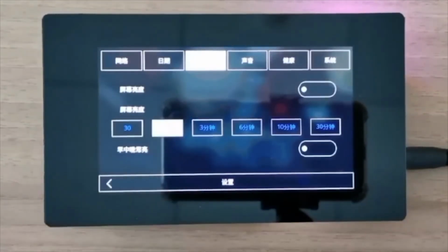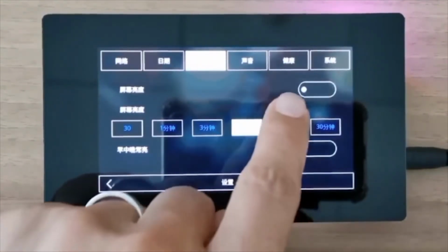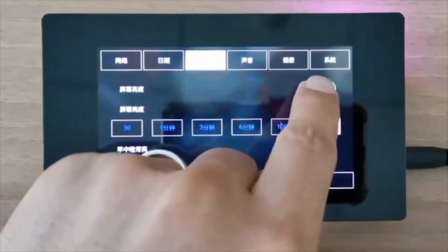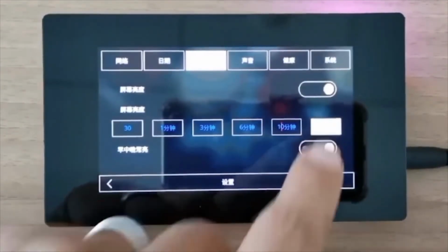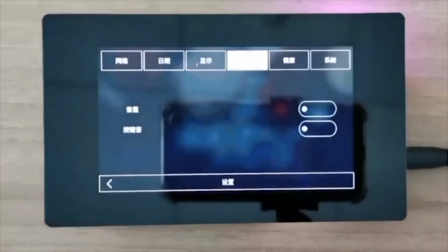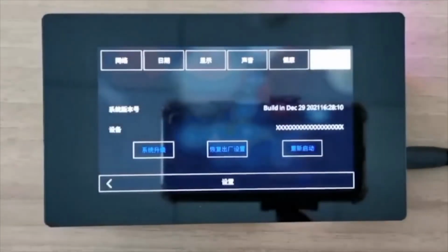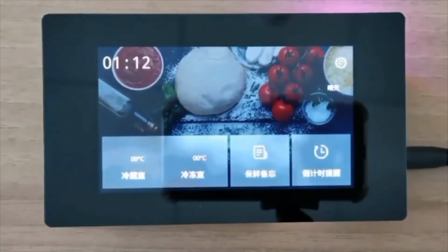The on-chip hardened MIPI DSI controller and Mixel MIPI D-PHY support MIPI interface display using less logic and power consumption compared to other platforms. And when compared to SoC platforms that support Linux or Android systems, the H1D03 FPGA supports faster boot and is more cost-effective. Mixel provided 2 instances of our 4-lane MIPI D-PHY universal IP, and HME achieved first-time silicon success.